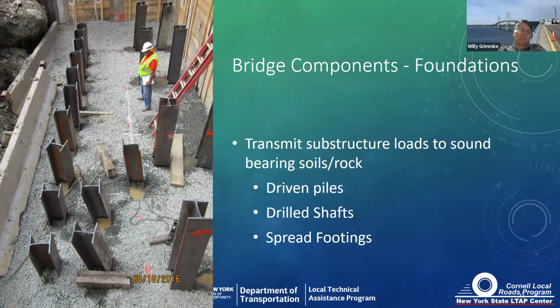In this photo, this is construction of a bridge foundation, which is on driven H piles. And these piles are driven through soft soils and to refusal with either firm soils or rock. We often have something like this where we're adjacent to active streams where we have potential for scour, so the foundation and the substructure won't be undermined in the event of a flood event.